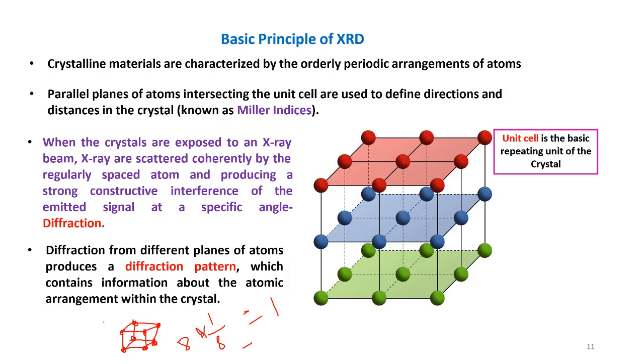So this particular cube will be having only one atom as its share, because 8 atoms are sharing their 1/8 part with the cube. So the total number of atoms for this particular cube will be 1. So that is the case of a simple cubic structure.